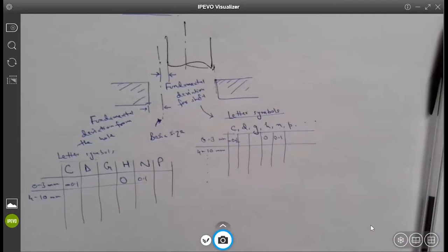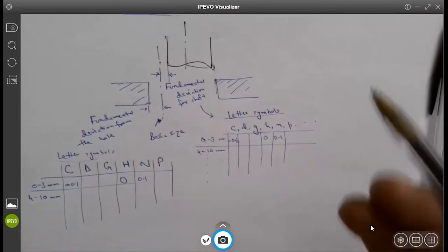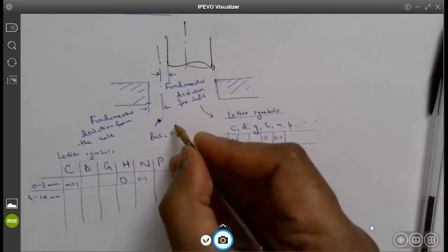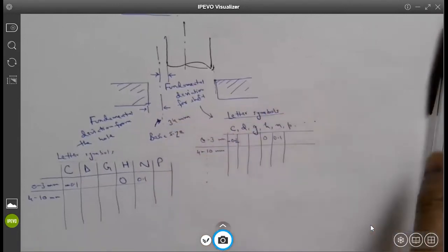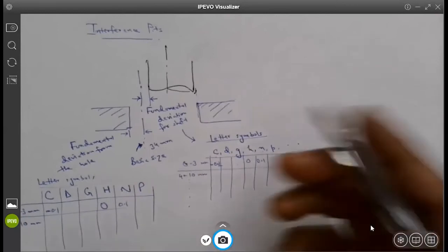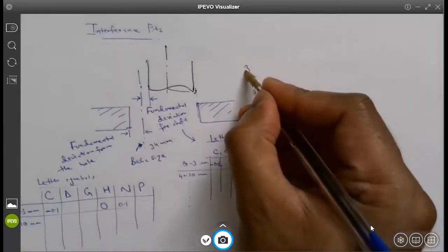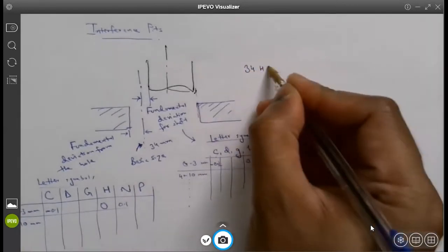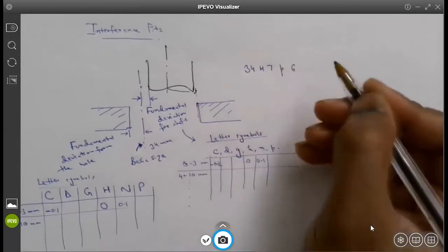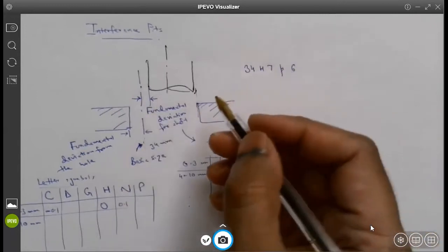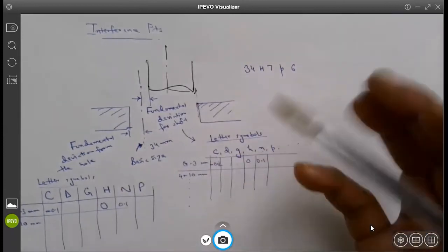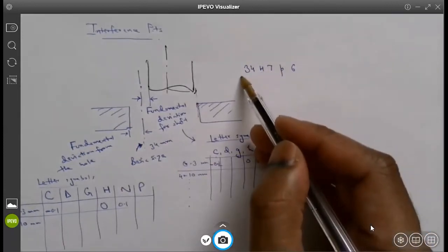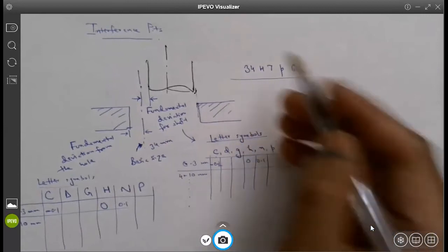Yeah, we're following it. Yep. Basically, if I pick a number, let's say 34 millimeters as my basic size, the way I see the tolerances represented is 34H7P6. That is how you will see it in the drawing: any hole or any assembly of shaft and hole is referenced by this specification, 34H7P6.